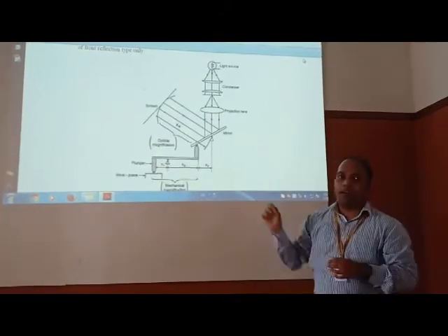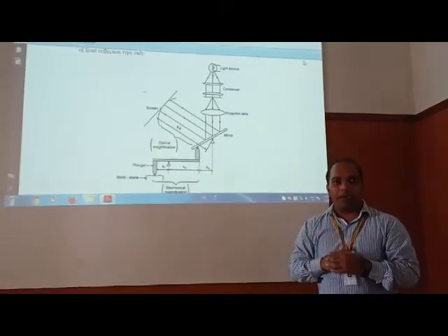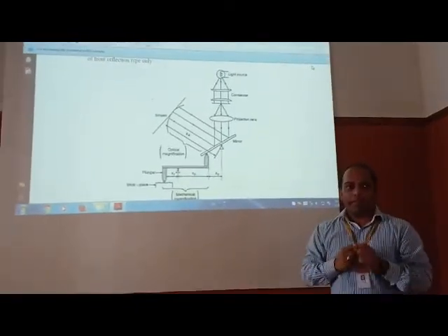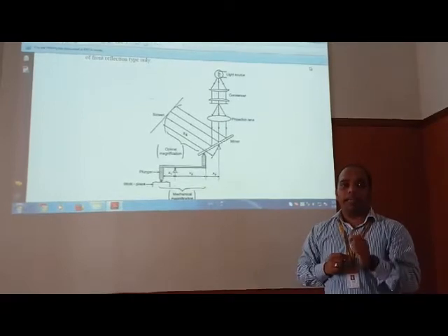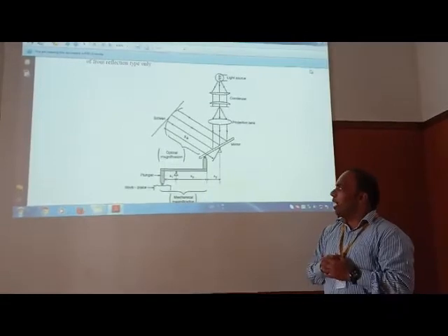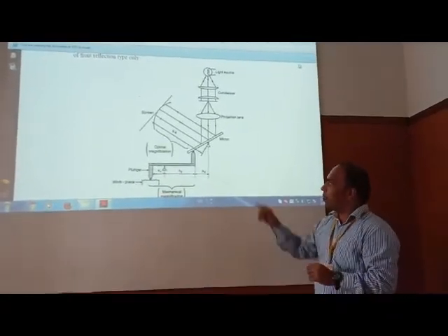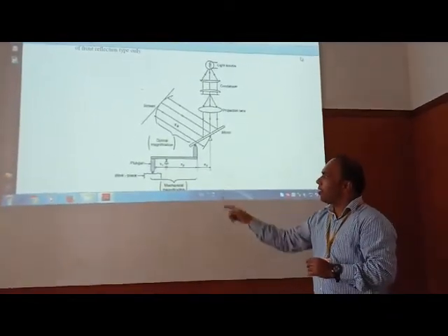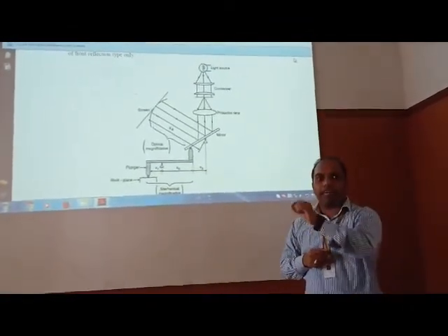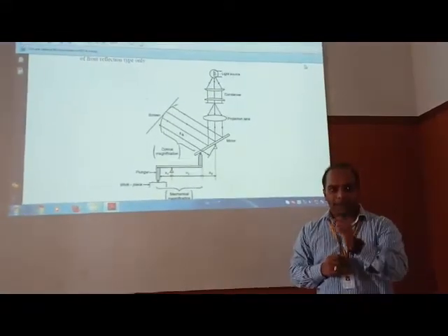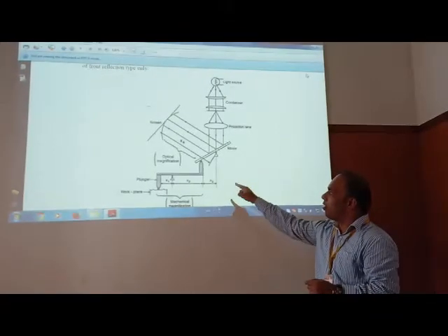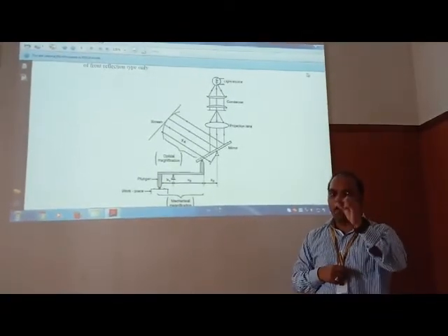The mirror is used for ray reflection of light. The screen gives an accurate reading, or the display gives the view or visibility. There is optical magnification which is obtained by plunger movement. Now we can see at the bottom our piece is having variations, that is, it is having some crests and some troughs which are to be noted by the plunger. The plunger will give a reading in the form of small movement.